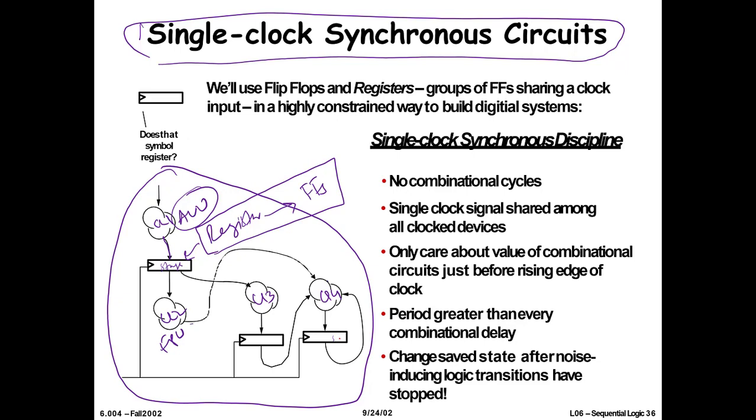So this is called single clock synchronous discipline, and all of your flip-flops are connected to the same clock. So this is one way to design circuits. You can use multiple clocks, that is also possible, but it becomes complicated to synchronize these clocks.